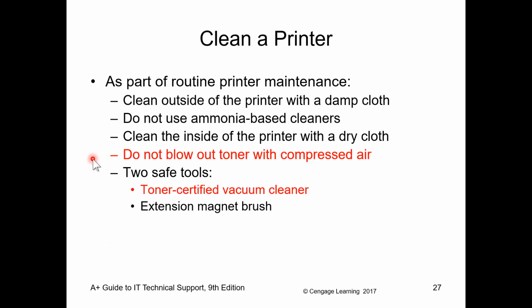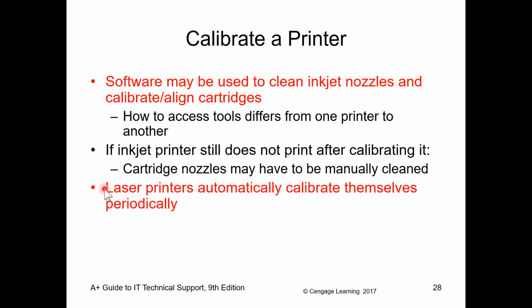You do not want to blow the printer out with compressed air because you don't want to inhale that toner. It's not organic. If you get it in your lungs, you've got little chunks of plastic in your lungs that your body's going to have trouble dealing with. If you're going to be cleaning it out, you need to get a toner-certified vacuum cleaner. You can get an extension magnetic brush because the particles are magnetic. They will be affected by a magnetic and electric field.